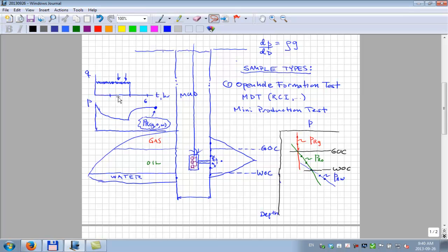This here is a mini pressure transient, and you can actually do analysis of that data. You have the rates, you have the pressures. It's not done very often, but it can be done. One of the problems is you have to take care of these wiggles because you actually have rate variations, and the analytical solution assumes a constant rate. So you have to do something called convolution or deconvolution, superposition, as you learned in your differential equation courses. You have to use the methods of superposition to analyze this type of data. Anyway, this can be done, and it's kind of a mini production test that can be analyzed.